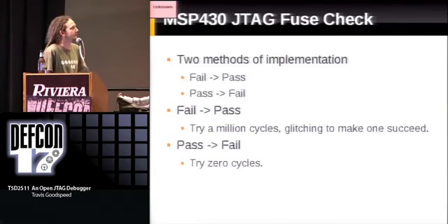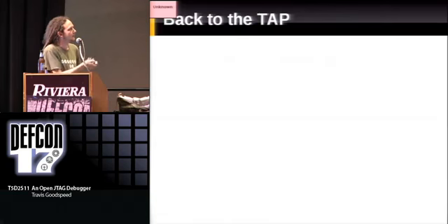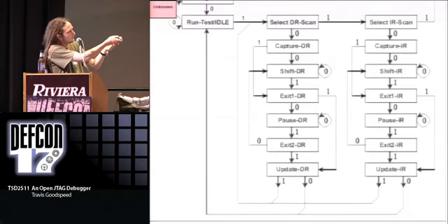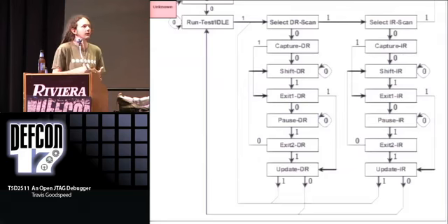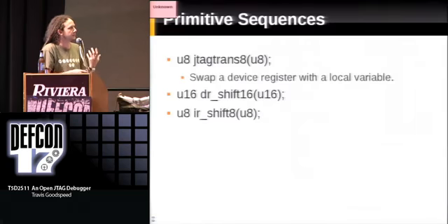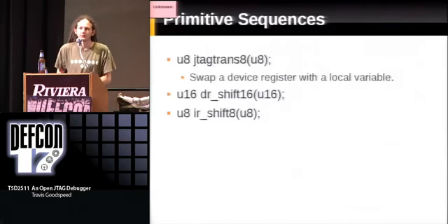So back to the state machine itself. You can see that each of these 2 columns is used for populating a register. And you can see that the 2 columns are pretty much just copies of each other, but one is further out from the idle state. If you wanted to add a 3rd register, you could, just by putting it further out here.